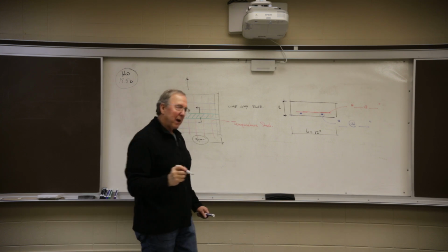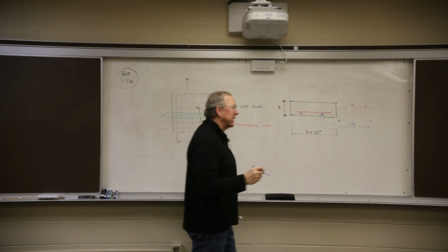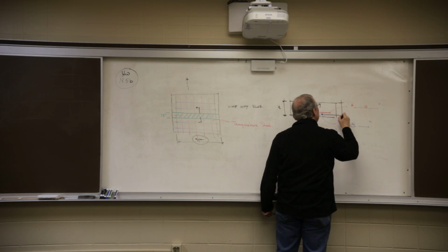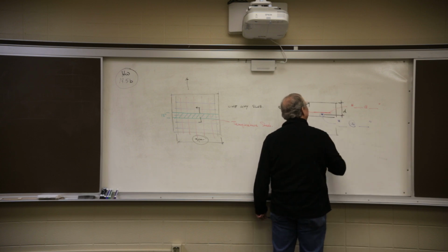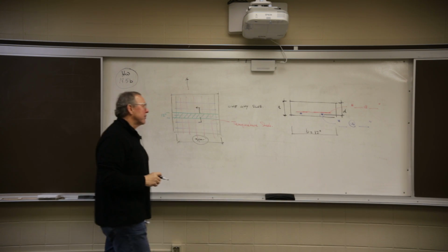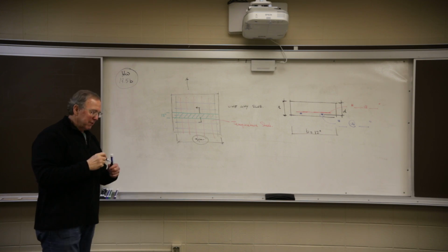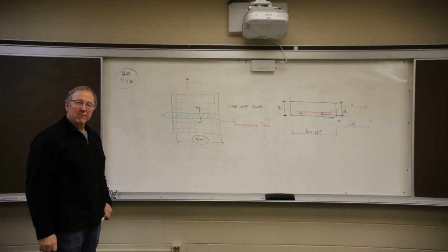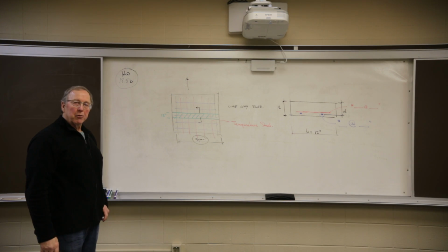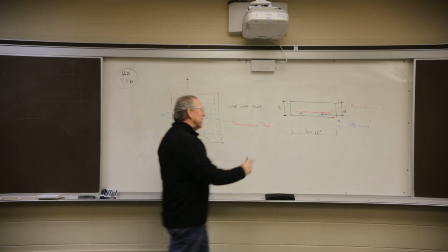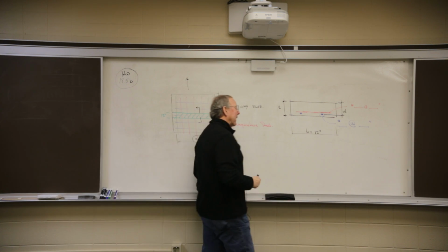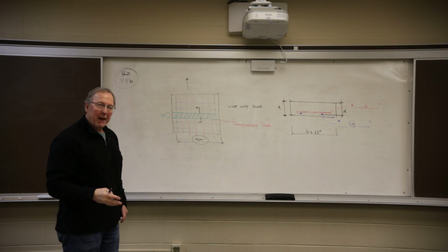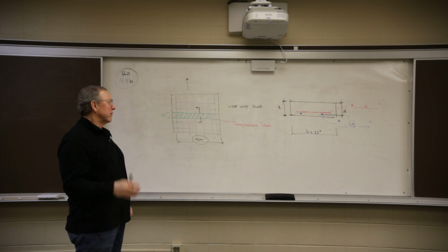Okay, like any other problem we've had, the thickness is not our determining metric. Our determining metric is the distance D, which is the effective depth, and that is from the top of the slab to the middle of the main reinforcement steel. So main reinforcement steel, you see how I put it on the bottom? I put it on the bottom because that increases D. We have to have cover. Of course, there's going to be cover there. We've got to have cover, so if I can get that main steel lower, that means the capacity of the cross-section increases in strength.